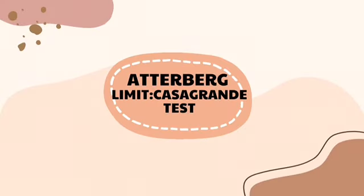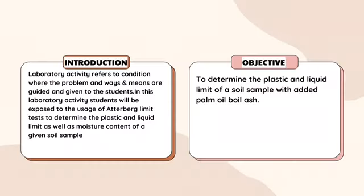Next, Atterberg limit, Casagrande test. Introduction. In this laboratory activity, students will be exposed to the use of the Atterberg limit test to determine the plastic and liquid limit as well as moisture content of a given soil sample. Objective: to determine the plastic and liquid limit of a soil sample with added palm oil boiler ash.